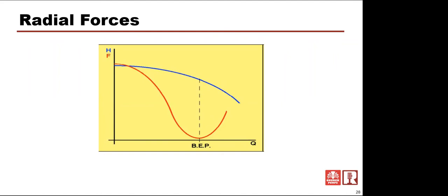It's a matter of one rotating and one stationary, and it's those two faces that close. If you start getting too much shaft movement, those faces can pop open momentarily as that shaft is being bent or moving back and forth, so you can start getting those faces to bounce. And when they start bouncing, fluid starts leaking out of that pump. So that mechanical seal, where the shaft comes through the pump from the motor side, begins to fail, begins to leak, and your customer's not going to be happy because they've got a pump that's